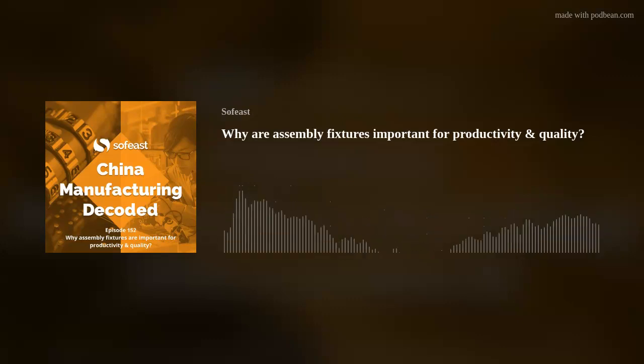You can't really do it without a fixture, or the part is just going to spin around, right? But if you allow the operator to put the part maybe upside down or in the wrong orientation, then if he does it 10,000 times, there are going to be mistakes, right? Five times in a row, maybe it's all good, but 10,000 pieces in a row, I'm not sure. So then you have a pin or something that actually makes it impossible to assemble the wrong way.